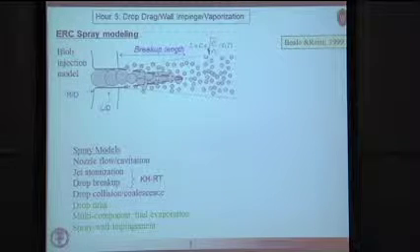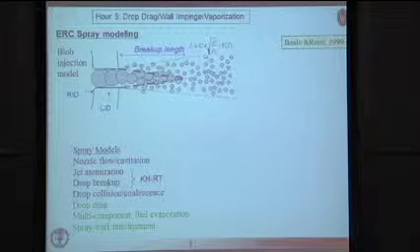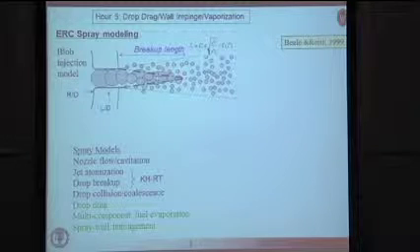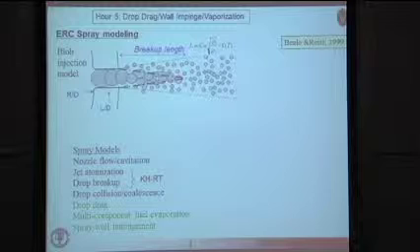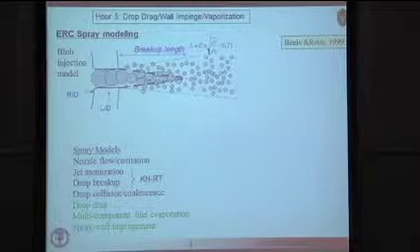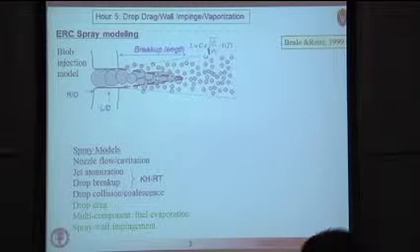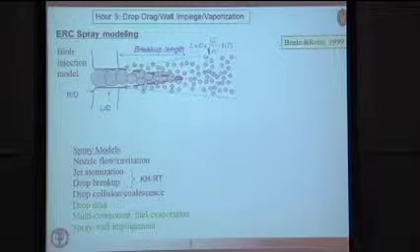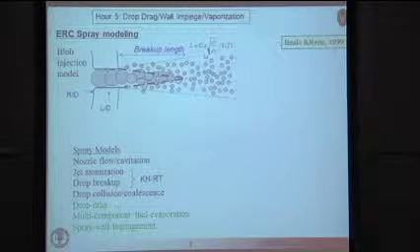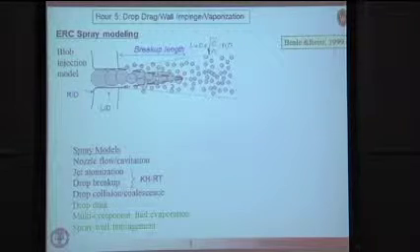So how do you go from that to a Lagrangian drop model? Well, we have introduced what we call the blob injection model. So we inject parcels of drops that have diameters equal to that effective nozzle diameter. And we allow those droplets or parcels or chunks of liquid, or blobs, whatever you want to call them, to break up using the Kelvin-Helmholtz and Rayleigh-Taylor models.